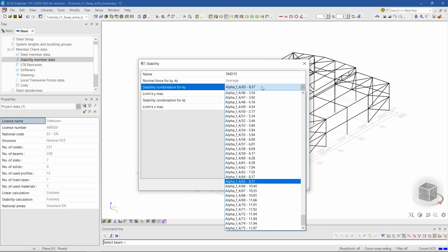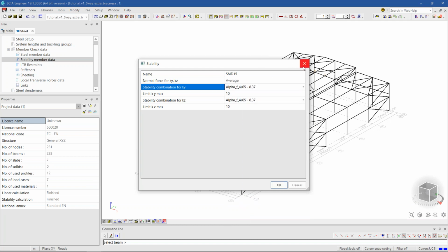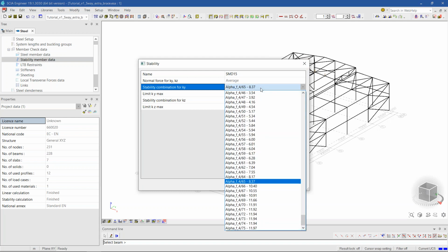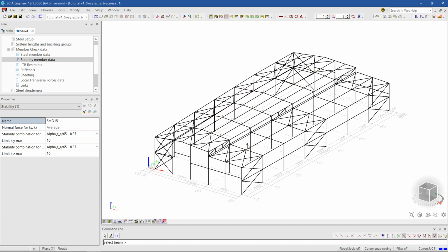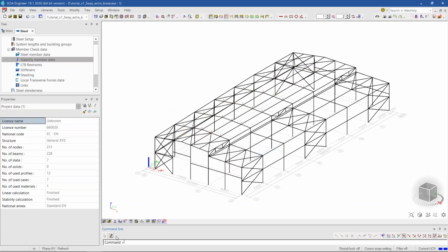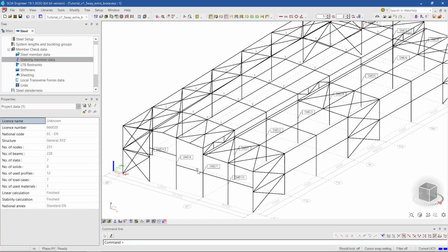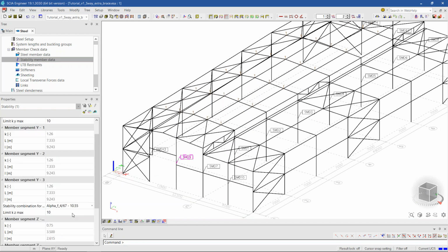To obtain that, instead of 75 modes, I may need to evaluate 150 modes and derive a buckling mode where this member is buckling. I will show you how to go about that and how we can get away from that limitation of the software. So let's say I have an example project where I've already inputted those attributes, the stability member data.